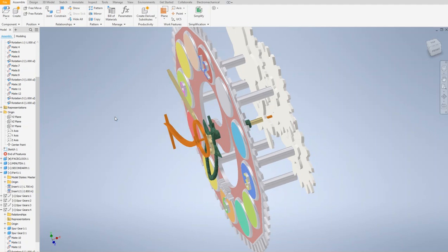Now we have to focus on the relationship between the minute arm and the hour arm. That relationship is 12x, or mechanical advantage of 12, MA 12. In order to obtain this within a reasonable size, we're going to break down 12 into 3 and 4. 3 times 4 is 12, and you're going to have 4 gears. 3 is going to command 2 gears, and 4 is going to command 2 gears, requiring 4 gears in total, and we're going to be connecting them.